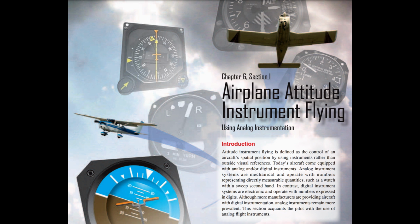Attitude instrument flying using the control and performance method. Aircraft performance is achieved by controlling the aircraft attitude and power. Aircraft attitude is the relationship of both the aircraft's pitch and roll axis in relation to the Earth's horizon. An aircraft is flown in instrument flight by controlling the attitude and power, as necessary, to produce both controlled and stabilized flight without reference to a visible horizon.